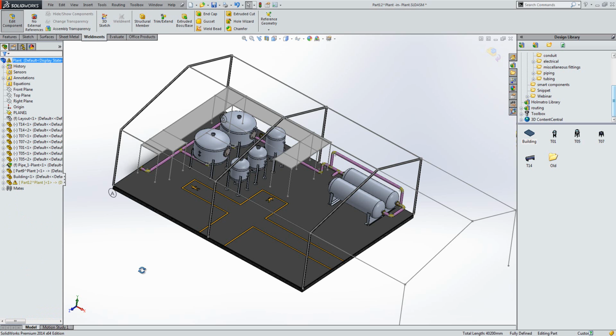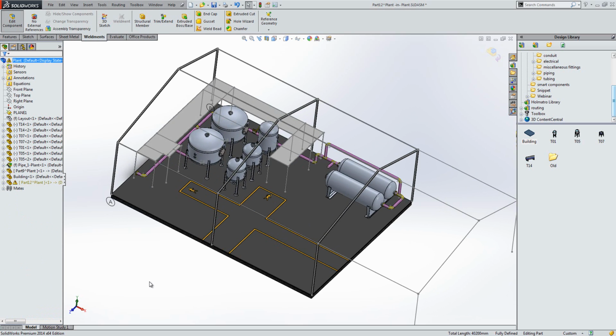So what we've very quickly covered is bringing in a 2D drawing and using that to place components that you've already got onto the model. We've then looked at using the routing pipework to join these items together, how to add in additional, more customized items, for example our raised walkway, and then how to set the scene for the customer, make things look a little bit more realistic with floors, diagrams and paintwork that could potentially be on the floor, and walls of one form or another, and also using the grid system.